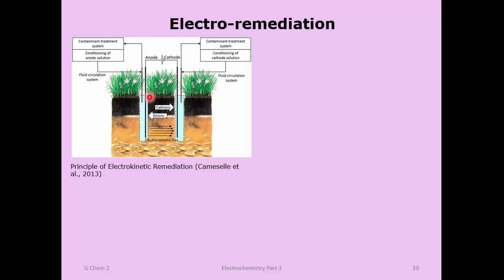And then you could basically get on the other side and keep flushing this. Either let the cations come out and deposit on the electrodes, or, this shows a kind of treatment system where you're actually purging this water as it builds up salts. And you could also imagine the same thing with anions. Say you have a nitrate or a cyanide, something that would be toxic in the dirt. You could move it out over here to the anode side.